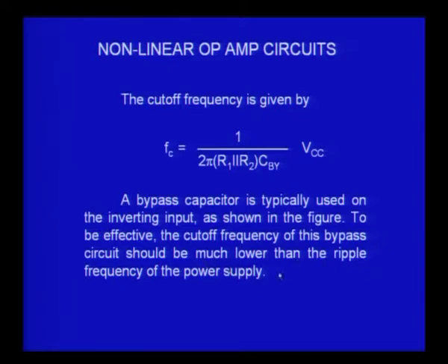When you use the cutoff frequency, you must make sure that the ripple frequency of the power supply etc. will come into the game, and therefore the cutoff frequency of this bypass should be much lower than the ripple frequency of the power supply.